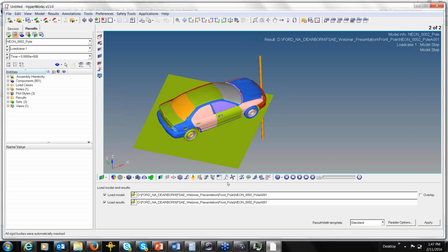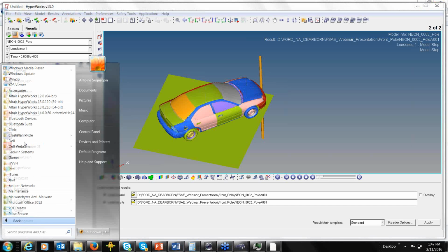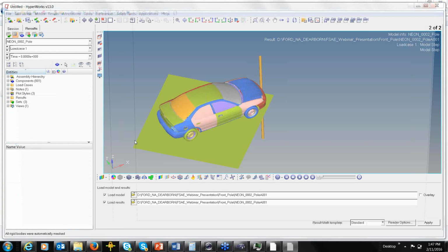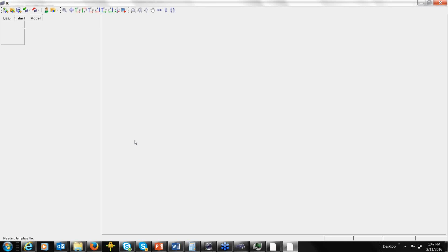In the OptiStruct model conversion from bulk to block, we have a tool built in that we call B2B, the bulk to block, where we take the OptiStruct model and convert it into a RADIOSS block model. That is done in HyperMesh. Okay. Just quickly, let me run through how the steps would be. Let's say I'm on HM. Okay, I have HM. You say it's a large model. It's going to require some work to do that.